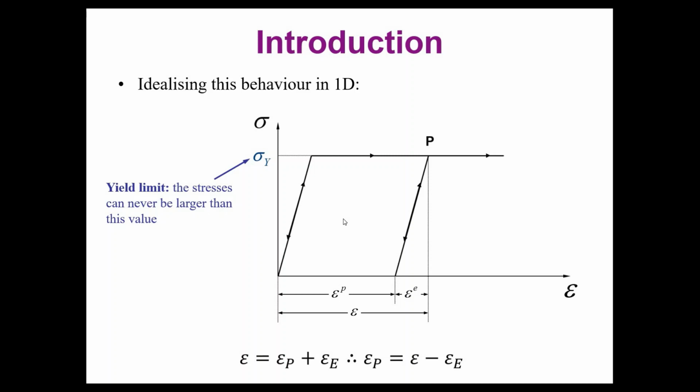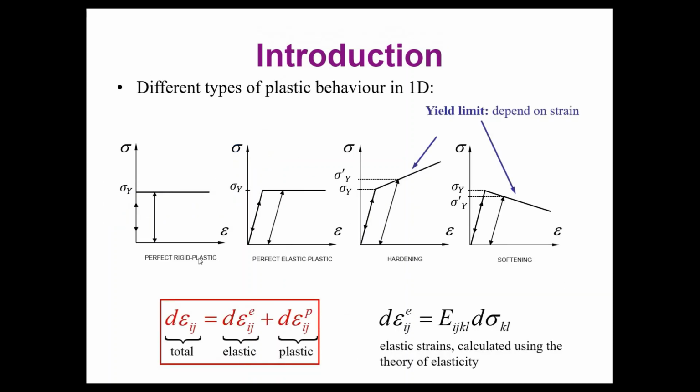Of course, this simple model is not enough in many cases, and there are others, and we are going to focus in this explanation on the bilinear model with hardening, because it's a very useful model in engineering, in civil engineering, and because it shows that it's possible to have a simplistic model that reproduces a ductile material behavior as we saw before.